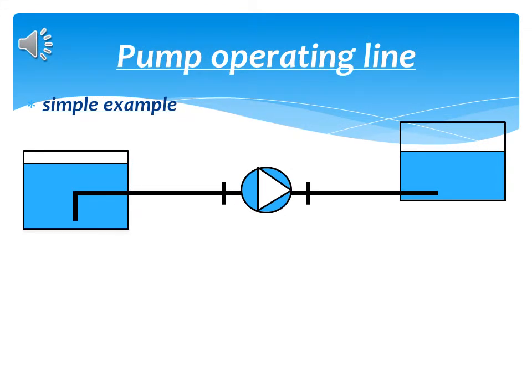The first section of this unit is the functioning of the pumping line. For this we will start with the calculation and explanation of an installation, where we can see two tanks, tank 1 and tank 2. The objective is to determine the operating point of a given pump that allows transport of fluid from tank 1 to tank 2. To do this, we begin by calculating the load heights H1 and H2 of the tanks, starting from the equation.